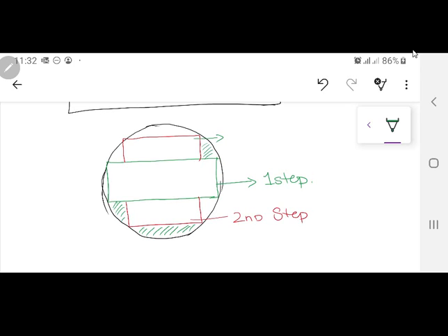You will first put an asbestos or a cylindrical sheet on it and then do the low voltage winding. Reason, because these are very sharp edges. If you put the winding on it, maybe the insulation on those copper wires peels off, and afterwards it will have a short circuit. So you will put a 2 or 3 mm thickness of asbestos or a cylindrical sheet, which will keep it in circular form.